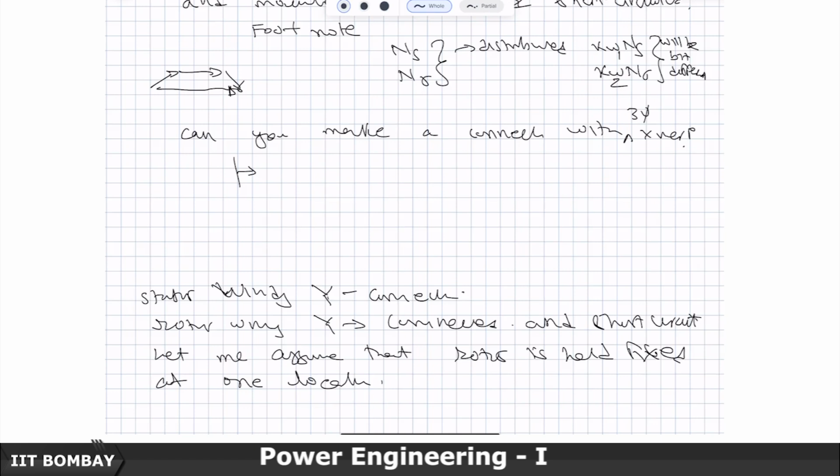The distribution in phase is not to create a 3-phase rotating MMF wave, because there is no rotating MMF wave of any kind which is created. Then you do not talk of something trying to move and all that kind of thing. The distribution is just vertically distributed in space. It does not create any real force or torque for it to rotate, and it just works as a simple plain transformer.